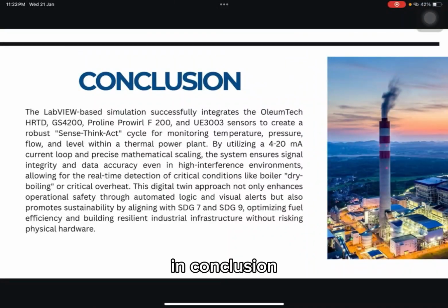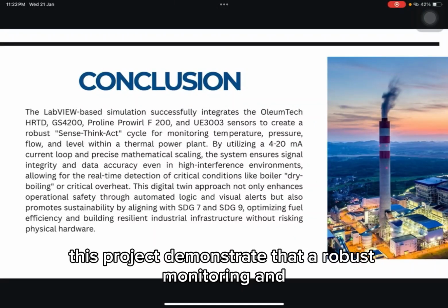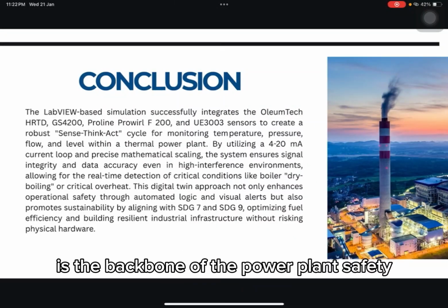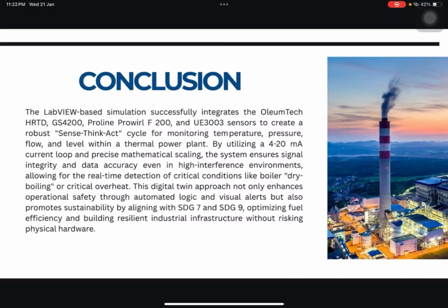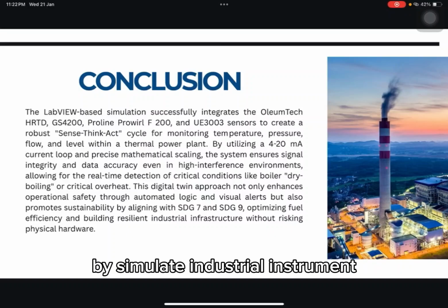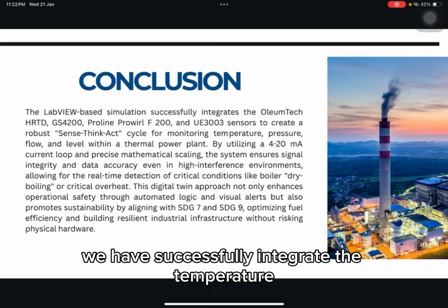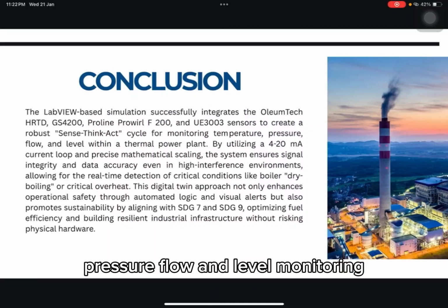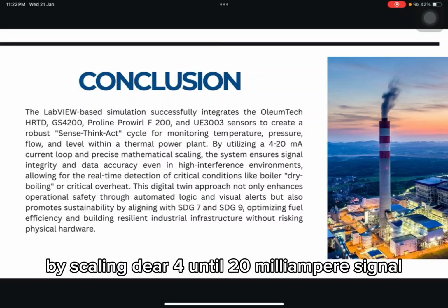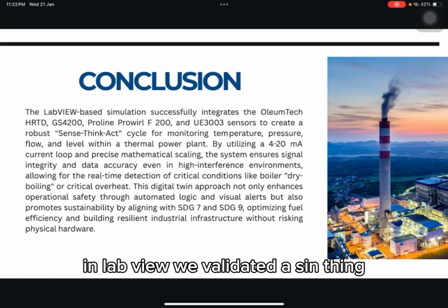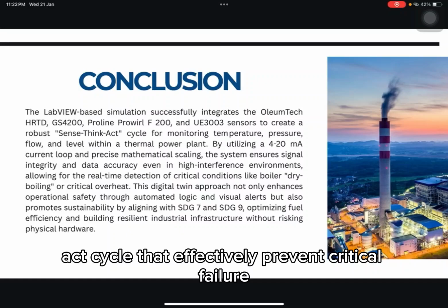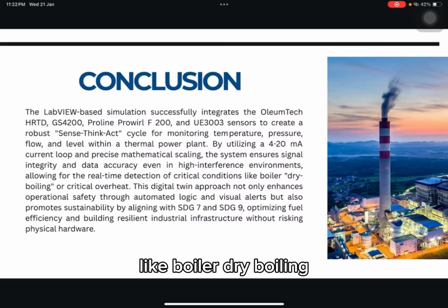In conclusion, this project demonstrates that a robust monitoring and control system is the backbone of power plant safety. By simulating industrial instruments, we have successfully integrated temperature, pressure, flow, and level monitoring by scaling 4 to 20 mA signals in LabVIEW. We validated a sense-think-act cycle that effectively prevents critical failures like boiler dry boiling.